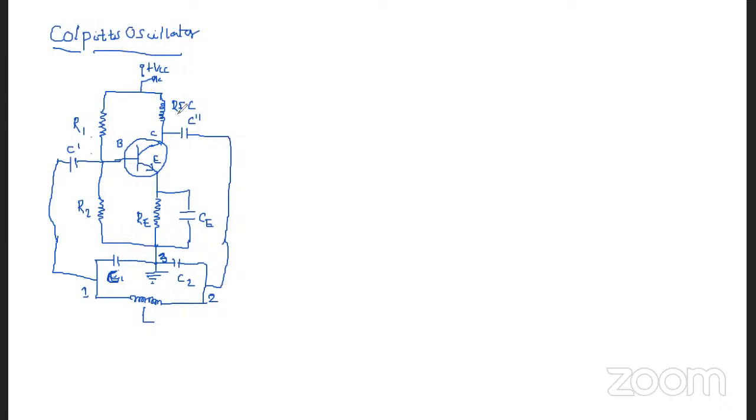And this radio frequency choke RFC provides the necessary DC load resistance for the collector and also prevents the AC signal from entering the DC.